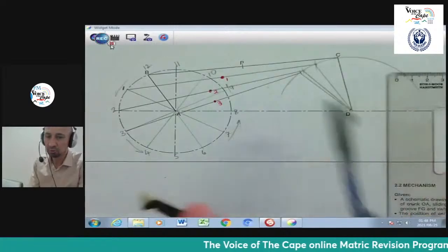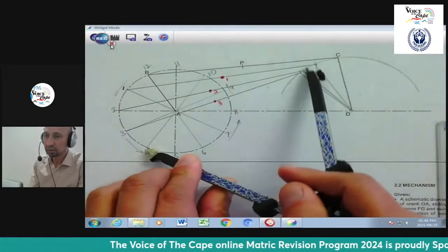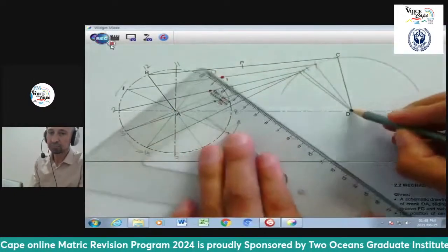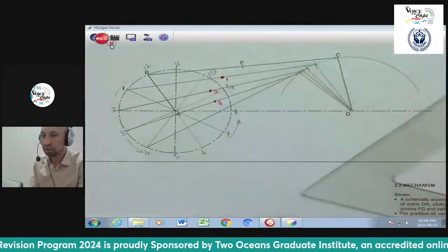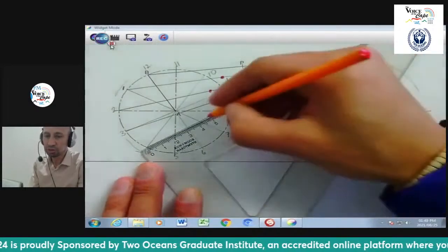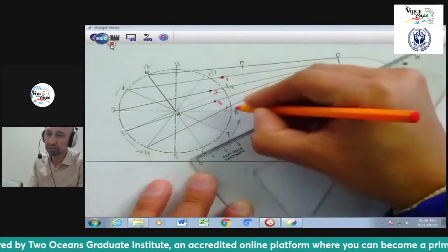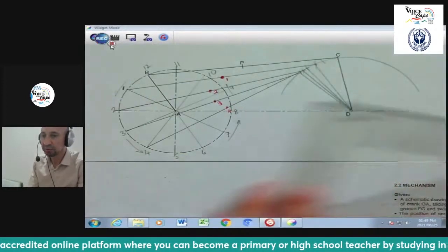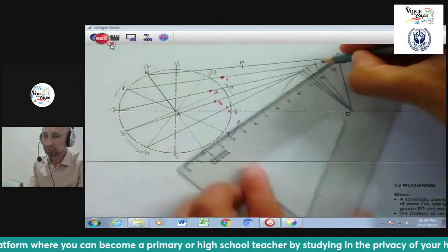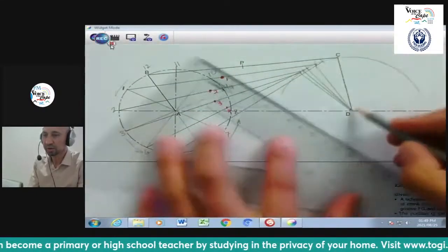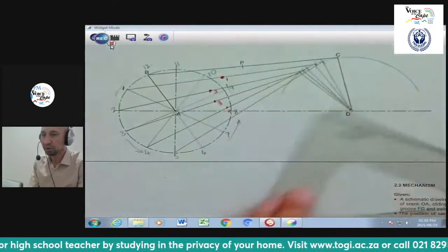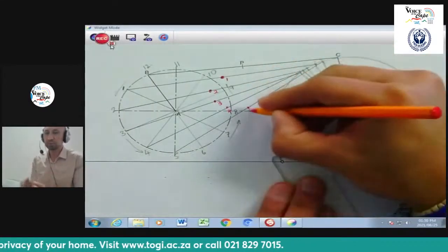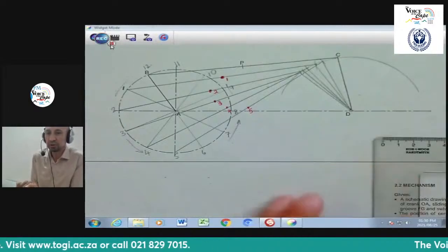You go to number 4, sharp point on there. It goes back now on here. So you draw your imaginary rod and your rocker there. And then, of course, your 63 again. That's number 4. And then you go with number 5, cut off number 5, draw the line to number 5 and to the fixed point of the rocker. And then you measure off 63. Simple. You follow that process because you understand it now. That's number 5. And then we go to number 6.